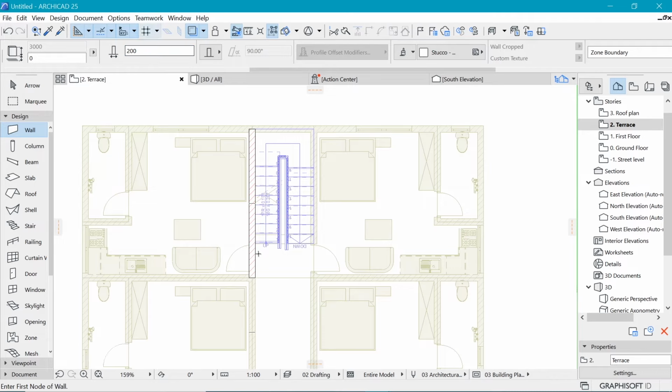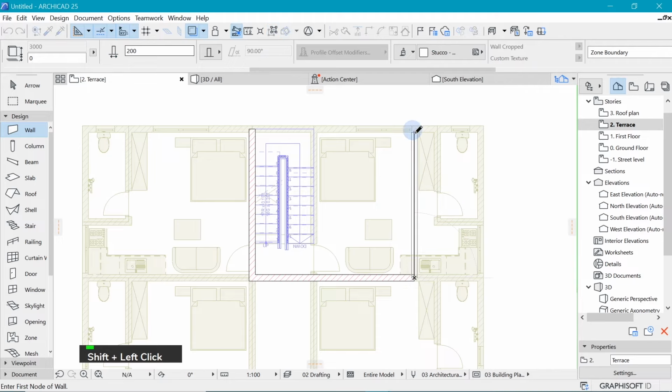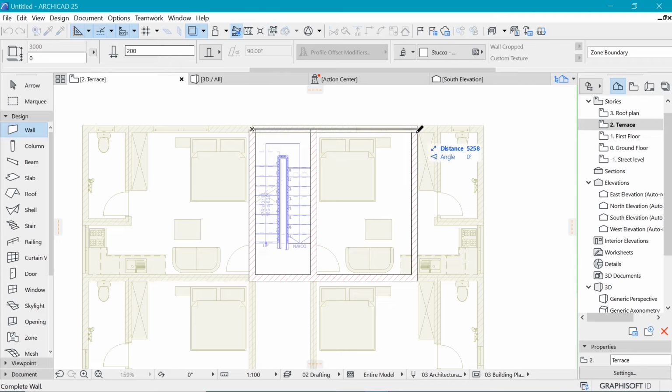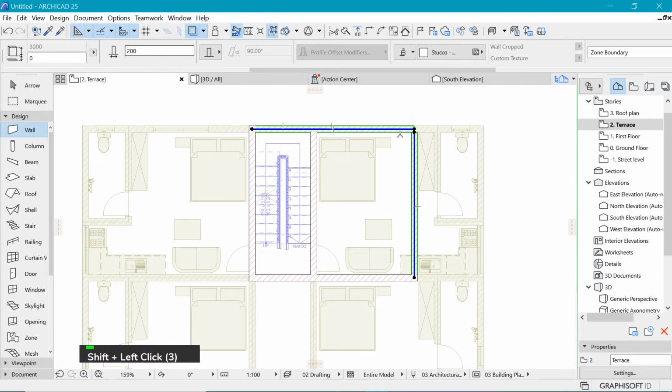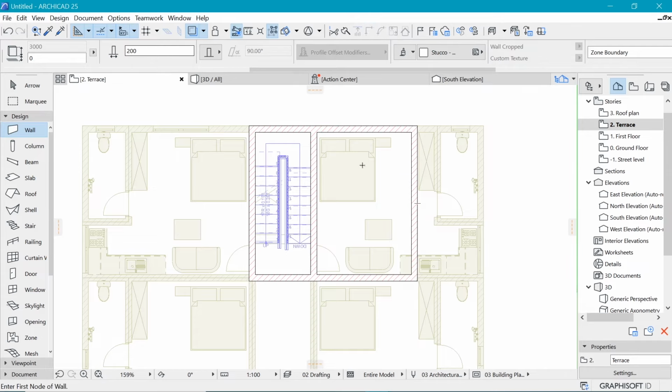Okay, and let's go all the way to somewhere here to there, because we have a room at this place here, and I'll close it off from this other side. And in order to intersect these, you can select both these walls and hit intersect, which is this icon right here, intersect, and those two will be intersected.